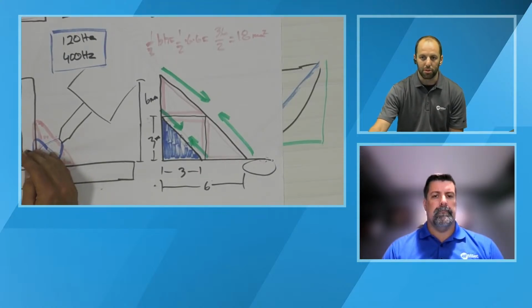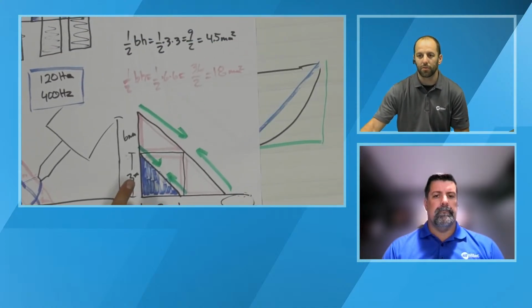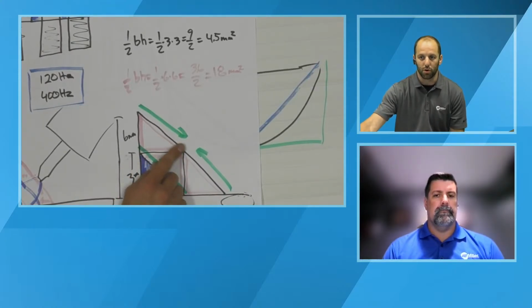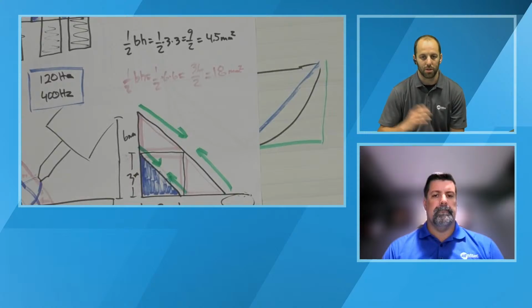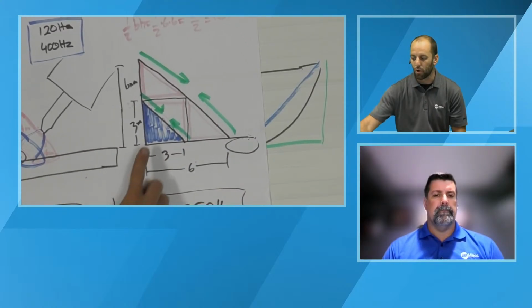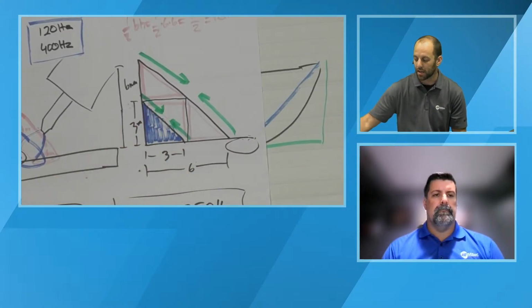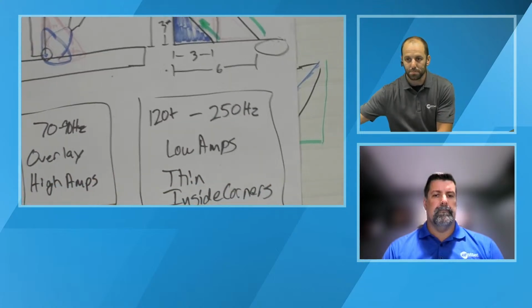Which means you're probably throwing more filler metal into that weld joint. We did talk briefly about the impact of the cross-sectional area, the amount of distortion that can happen in the part, which leads to rework on the backside of a component, as well as the direct cost of filler metal in that welded component by over welding something compared to what it was designed for,